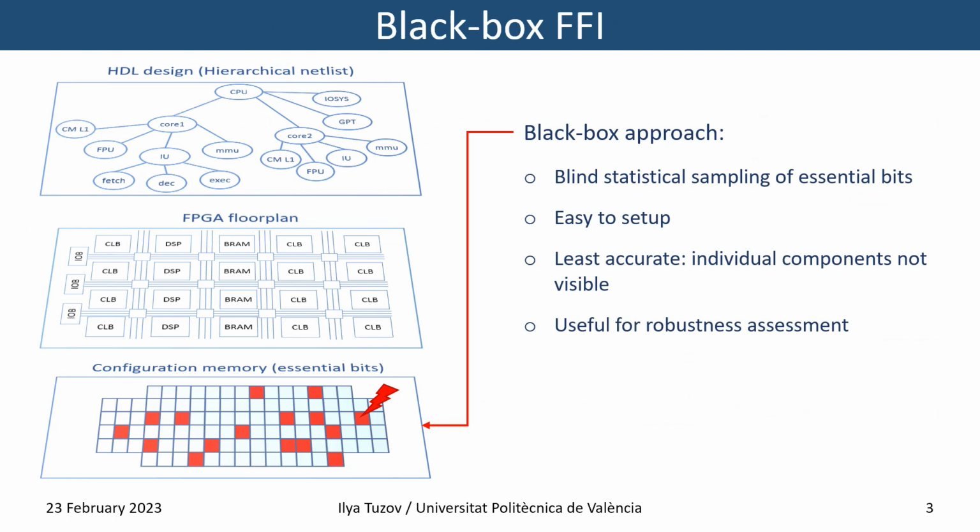For this reason, many fault injection tools rely on the black box approach. Its idea is basically to blindly sample essential bits. Essential bits, in the Xilinx terminology, is a subset of configuration bits that determine the circuitry in FPGA. So only injection in essential bits may have any potential effect on the design behavior.